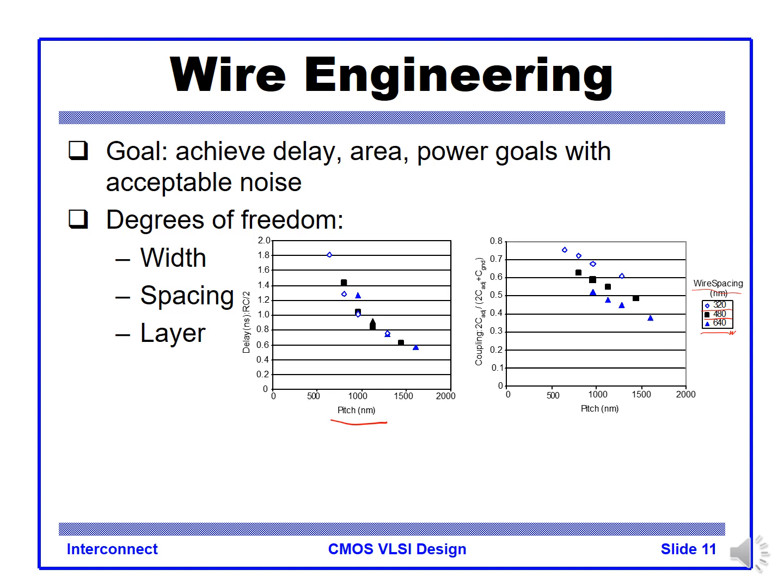When the wire spacing is narrower, smaller, you have lines in parallel, so you get the slowest, largest time constant delay. And with a larger pitch, you will get a smaller delay, right?